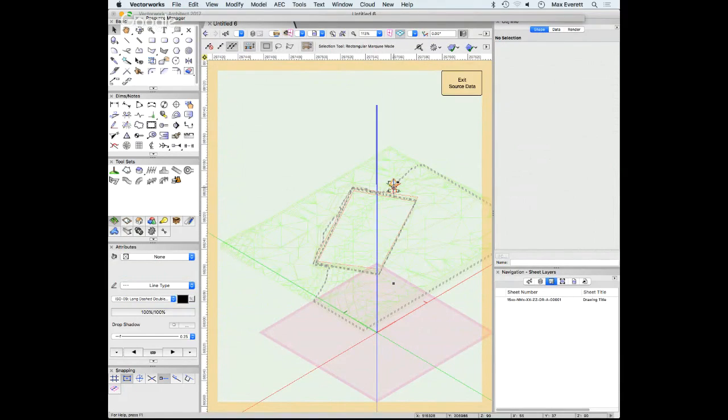Well, it definitely shows clashes where you've got two pads at different levels. Yes, the pads are too close to one another. They overlap. But I'm not sure if it shows it in this. So you can edit the source data. There are ways of creating sites from text files as well. So if you get a text file with raw data, you can input that information quite easily. If you haven't bought a site and someone has the spot heights as a text file, you can create one and it creates all the 3D.